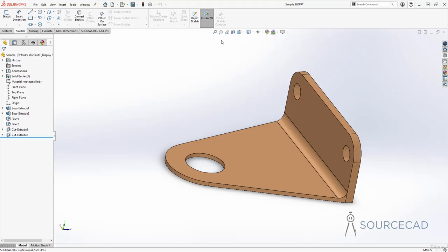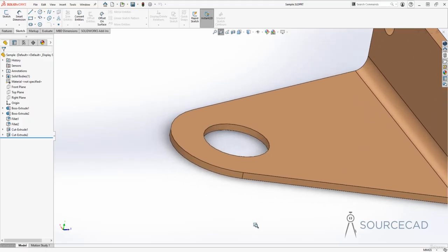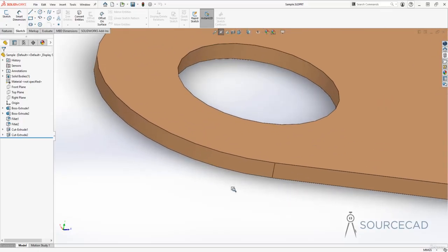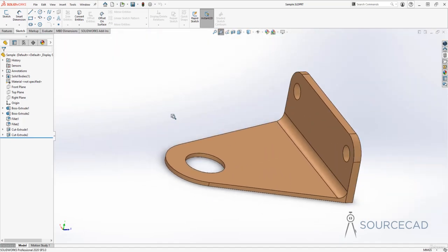Then we have the next option, which is called zoom window. So select that and make a window, or just select an area and it will fit that area in the drawing view. So basically this is zoom window or zoom area. So you've got to specify an area, it will fit that. So now we are moving out of the view. So I'll click on this fit option to fit it properly.